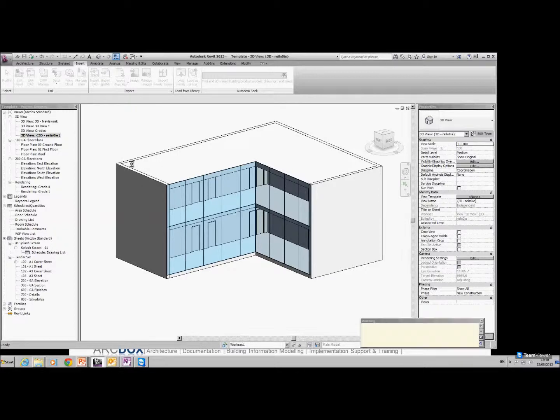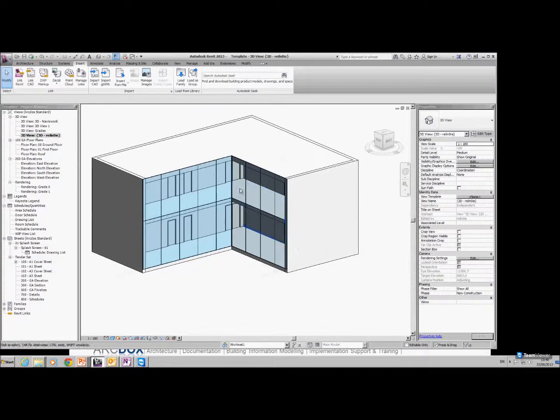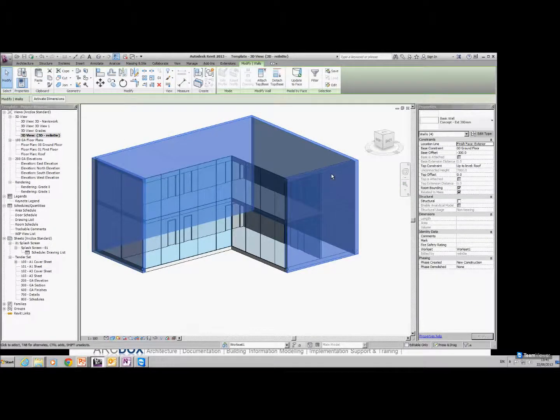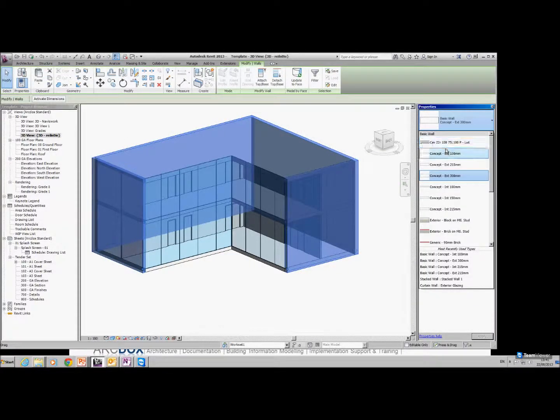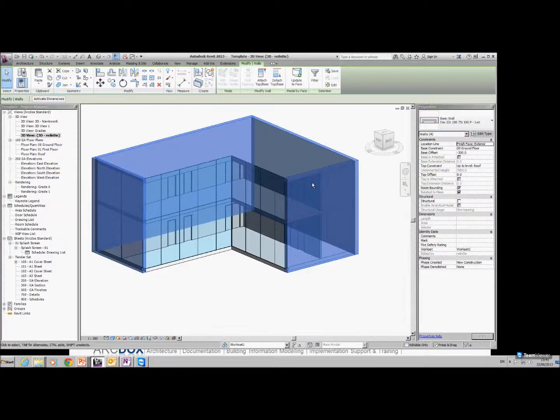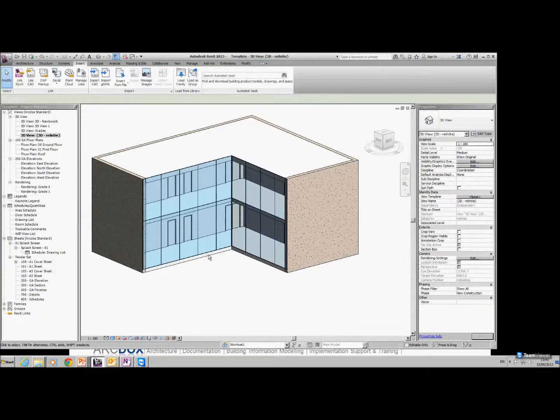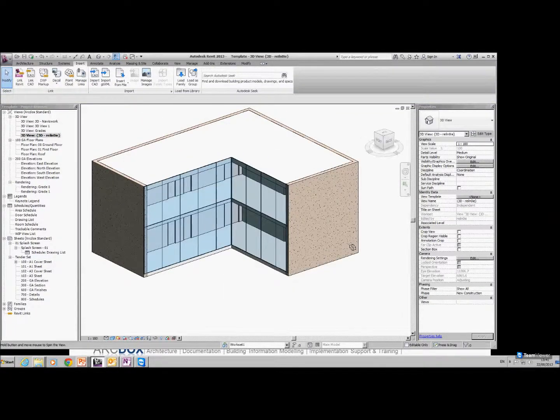What I'm doing is actually loading in a wall type, a floor type, some materials, just to bring this model on. So this is grade 1. I'm going to develop this to grade 2 now. So I'm highlighting all these walls again, over here to my drop down, and the only model I want to use is this cavity. Loaded. This wasn't here before I loaded in that group. So I'm just clicking on this, and now if I deselect, you can see it's after changing that wall type.